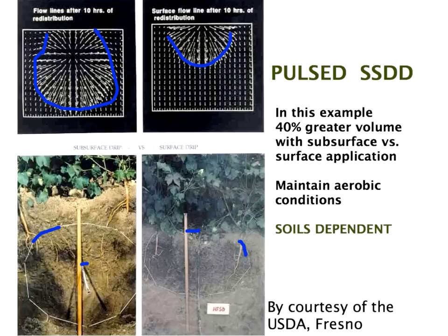And when you're pulsing, you allow the capillary action to move the water sideways and up, as well as gravity plus the capillary action taking it down. And if you look, that distance, sorry I went a little far there, is only a little less than that distance. It is less. And as you can see, that's about in the middle. But now we don't get perfect soil like that, but the principle is the same.